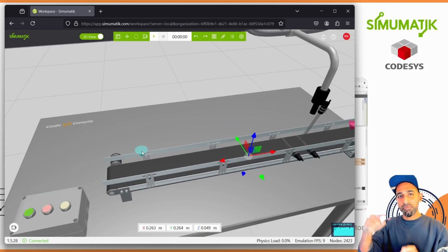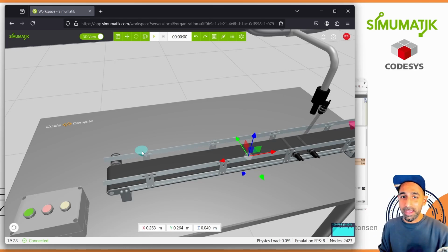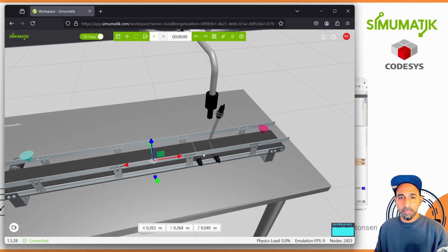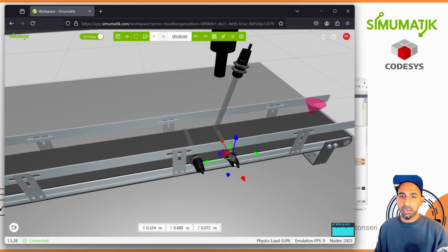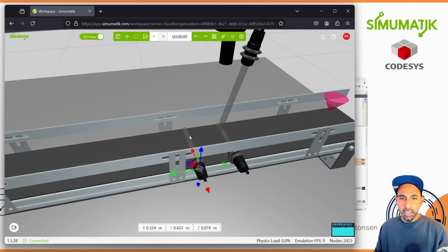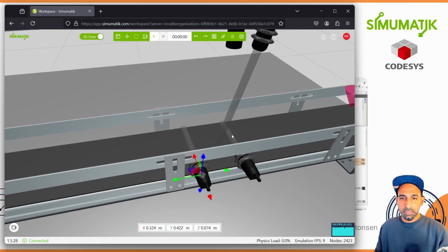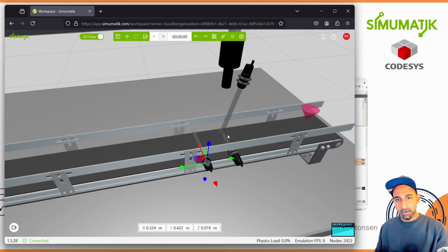So it will drop some products. I created the can, and this can is a very special can. I'm going to tell you shortly. The can will come here, and then it will travel on this belt conveyor. Then you have these two sensors, basically photoelectric. When the can passes, this sensor will be true, and this will get false. With this condition, I stop the can.